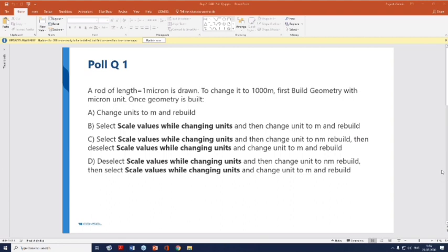In today's stack question, I need to have dynamic control. So if you want to have a dynamic control, in the sense that it is based upon the value, then you can specify the number of fins itself as a parameter. While creating that linear array, when we are having those circular objects stacked one above another, you can directly provide the number of fins as well as the spacing between the fins based upon the parameter itself.